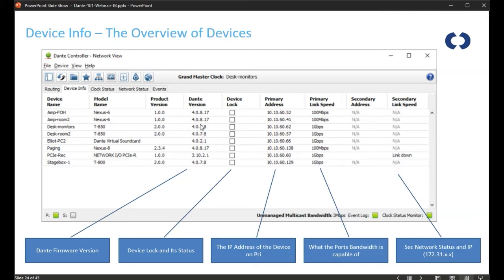And when you do a Dante firmware update, it's really risky. One of the things that Dante is very good at is, in very generalizing terms, the firmware that's on there is normally perfectly fine. If the system is not broken, don't touch it, leave it running as is, and don't do the firmware. So unless there is a feature that you require that the Dante firmware will enable, or the manufacturer of that brand told you to do the firmware update, you generally don't do the firmware update unless you have to.